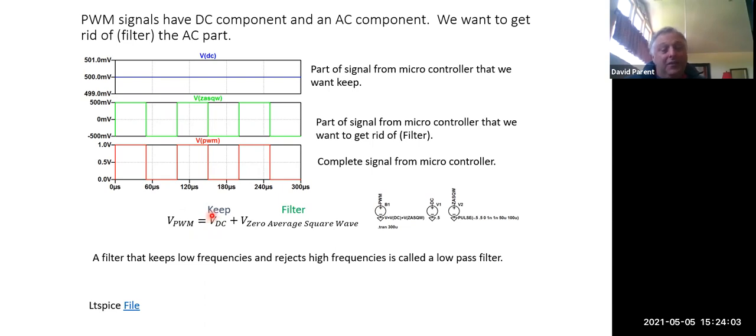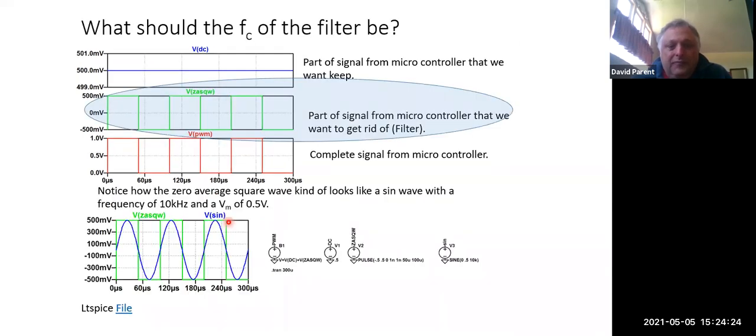So in a way, it's a trick, because this signal doesn't exist for all time. It just exists for long enough. What's long enough? Well, for a low pass filter, 5 tau. So we have to get rid of this part with a filter and keep that part. That means low pass.